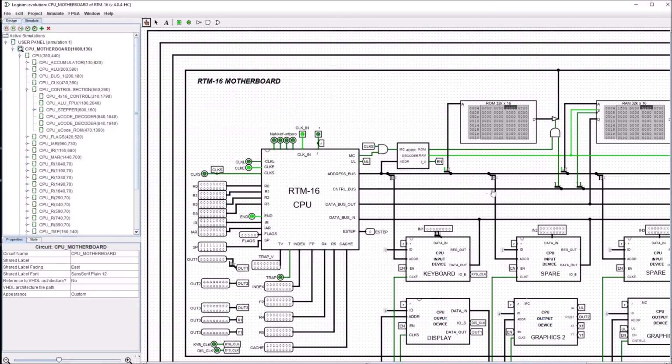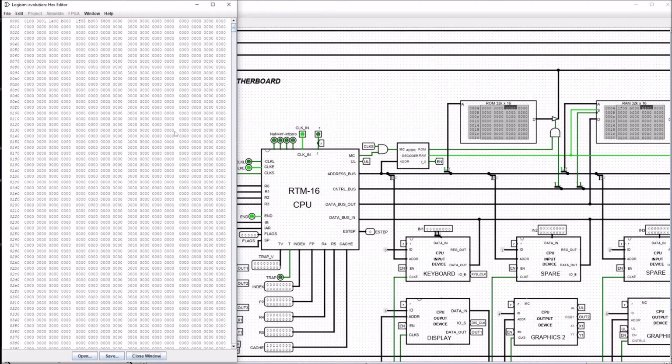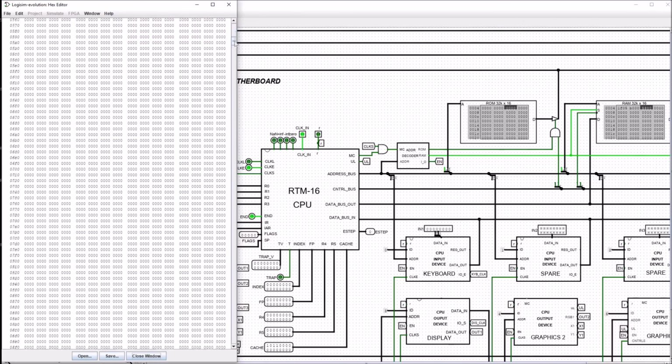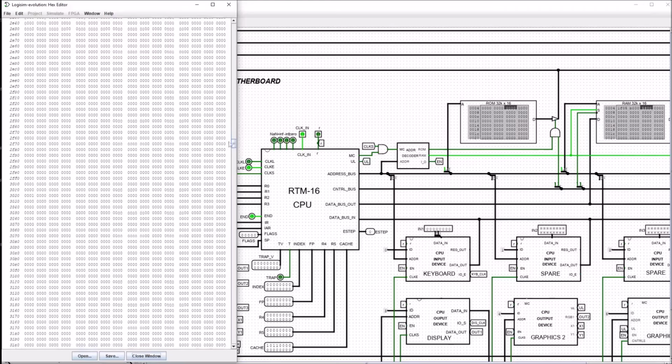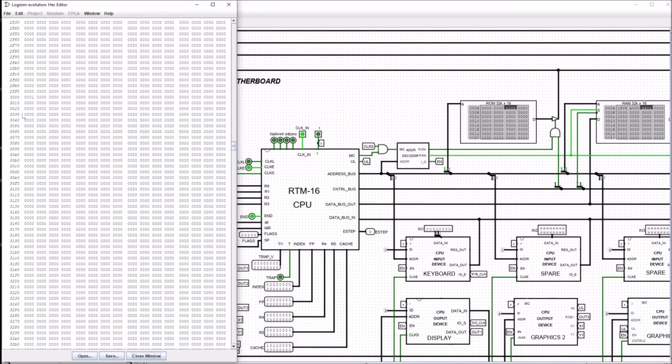So let's have a look at the actual memory location, which is going to be 0xB000, which should be 3000 here. So that's 3000. So you can see at 3000 we've got the number 1. So it's done exactly what we want it to. So now we've got an extra couple of instructions that can move content from a register to a memory location and a memory location back to the register.